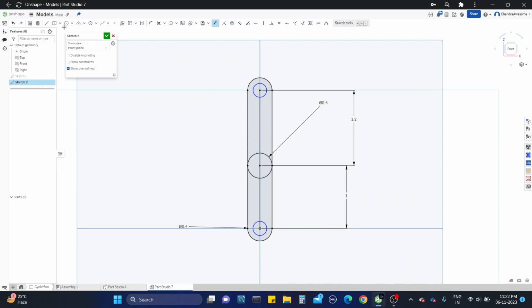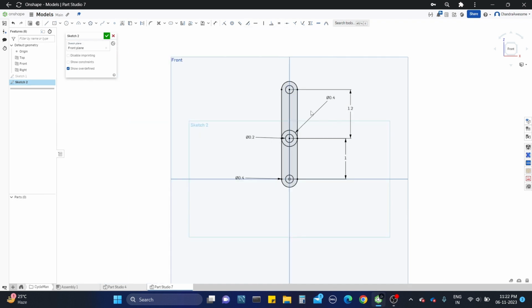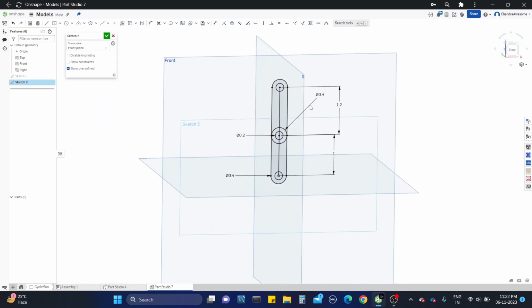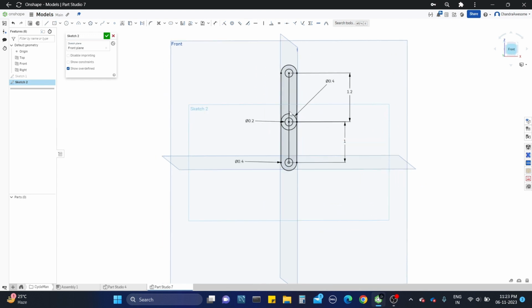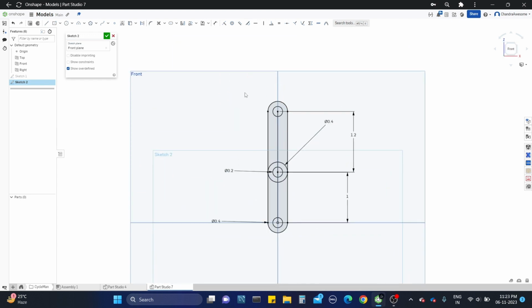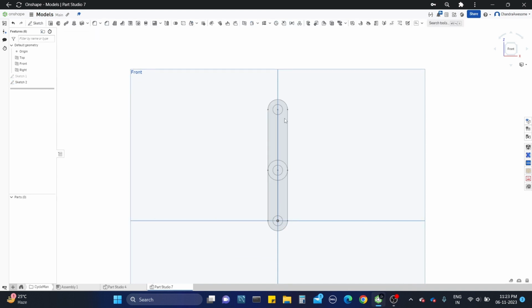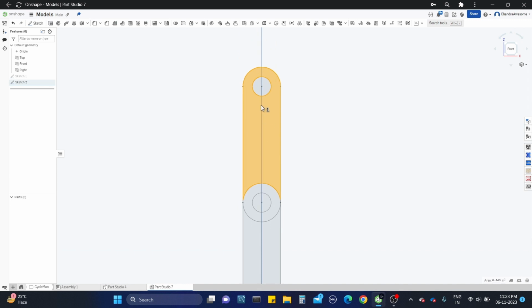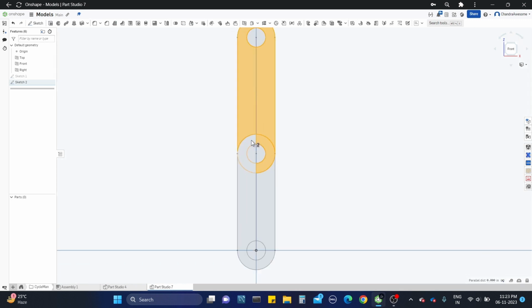Okay, so we need to add a circle here because we need a joint here also. Now let's give a dimension: 0.2. Now I'm selecting these and clicking on the equal constraint so the 3 circles get the same dimensions. Okay, so these are the legs we need. These are the main parts we need to work with here. Okay, and sketch and extrude the frame to 1.